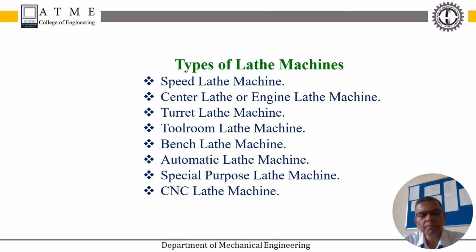Right. The speed lathes are generally smaller capacity lathe machines for simple jobs and with minimum operations. For such kinds of jobs, the speed lathes are recommended. A higher depth of cut cannot be recommended for these speed lathes, because only light jobs are recommended for them. Similarly, there are the engine lathe, turret lathe, and tool room lathe.